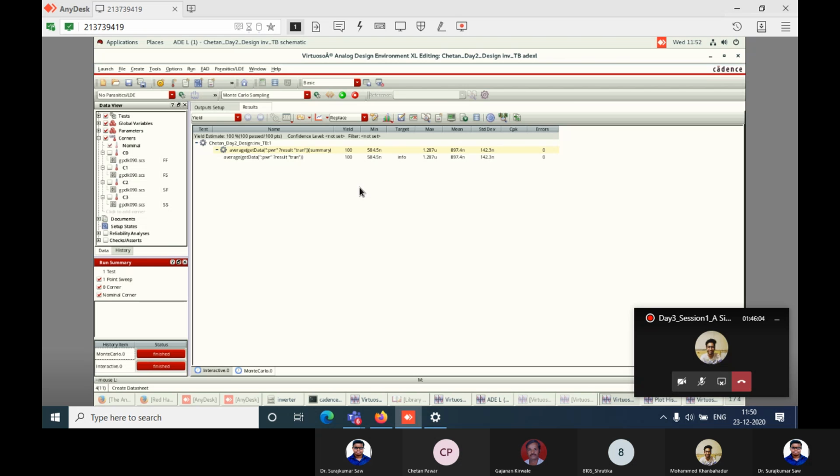Are you able to listen to me? For the next 1 hour, you just practice the NAND gate that you have done yesterday. You do the advanced simulation of that NAND gate. You perform the corner analysis as well as the Monte Carlo analysis for the NAND gate, like average power and delay, just in the same way we have done for the inverter. Just follow the same for the NAND gate. You just close this tab, open the previous one that you performed yesterday, and do it.